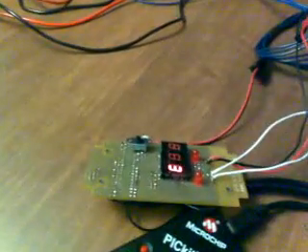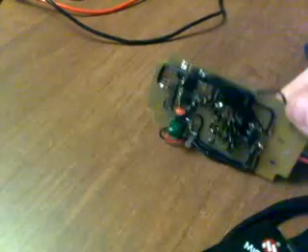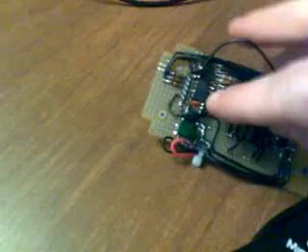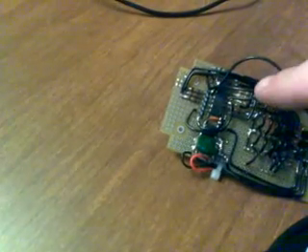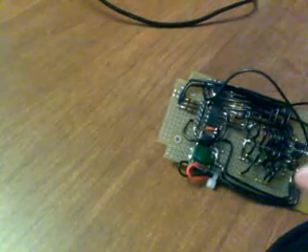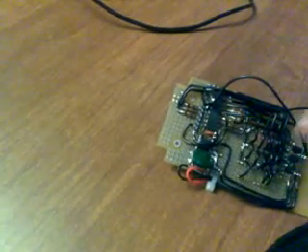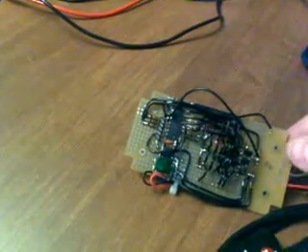I built this piece of hardware out of about $20 worth of material, including some old 7-segment LEDs that date back to the mid-80s. There's a PIC microcontroller and a filtering circuit. The PIC is outputting to some transistors that power each one of the displays individually, and they turn on and off really fast so that they look like they're concurrently on.